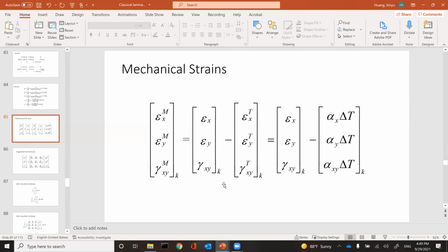If you think about it, if the fiber is running this direction and the matrix is running this direction, if you give a temperature change, which part can go fatter? That direction. This direction is really constrained by the fiber, right? And if you orient this lamina this way, this lamina wants to expand this way very much. Different layers want to expand different amounts. They actually fight. This is called thermal stress. You don't even need to load it. You just change the temperature.